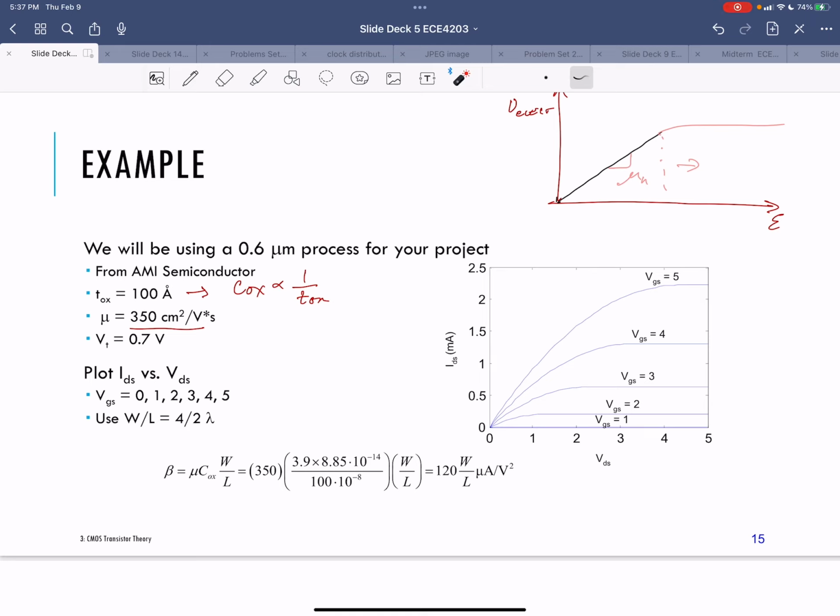And again, it's a pretty good model. Although it's not accurate for a 40 nanometer transistor, I still keep this model in my head because it's still indicative of a lot of things. For example, I know if I want to get double the current for a transistor, I'm going to double the width of the transistor.